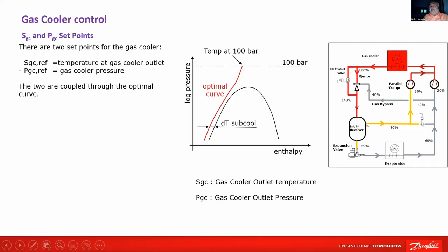Now, once you are here at higher pressure, you don't have to put it to the MT compressor. I'll put a number. Let's say this is working at 38 bar, like a water chiller, 38, 39 bar. Now we can lift it by 10 bar to 40 bar. Okay, it's an absurd example. Let's say 6 bar, you can lift it to 16 bar. So this compressor will run from 16 bar to 90 bar. This was running from 6 bar to 90 bar.